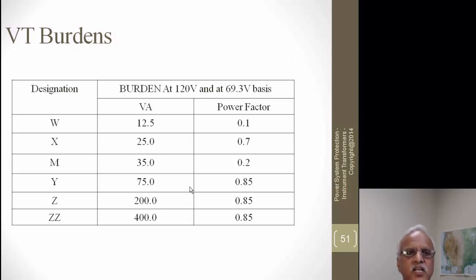And the potential transformer and the regular transformer, what is the difference? You are reducing the voltage from a very high value to 66 volts. Let's take an example of 230 kV. 230 or 115, these are typically phase to phase voltages as defined in the standard for a three-phase system. The phase to ground voltage is phase to phase divided by square root of 3. So it is 132,000 volts for a 230 kV system, and that is stepped down to 66 volts. So the ratio is 2,000.